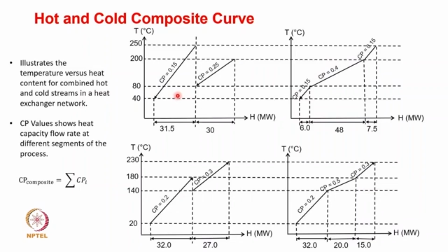So these are the two composite curves of the streams, and whatever we have written are their corresponding Cp values. These are the H versus T curves for the individual streams. Now we are going to draw the composite curve of these two together. It starts from here. From here up till here there is no effect of the second stream, but in this regime you have two streams together. So we will have to join these streams together, and after that this stream is standalone.